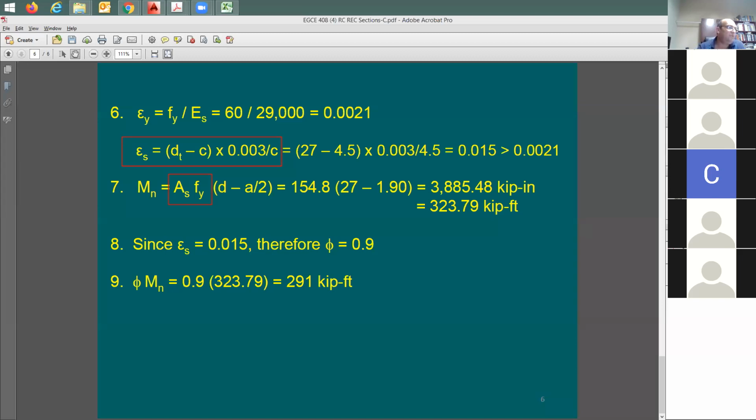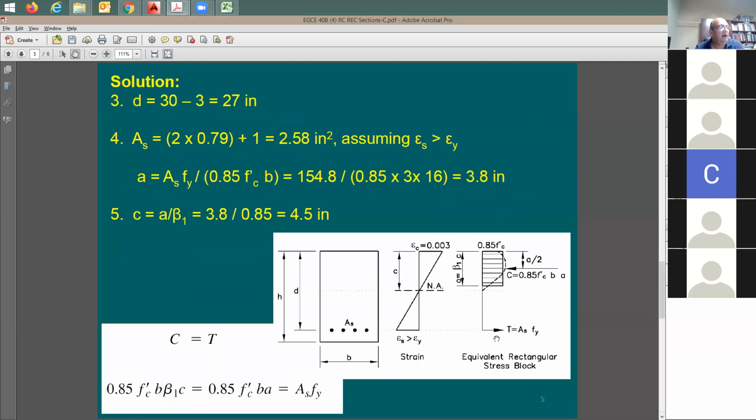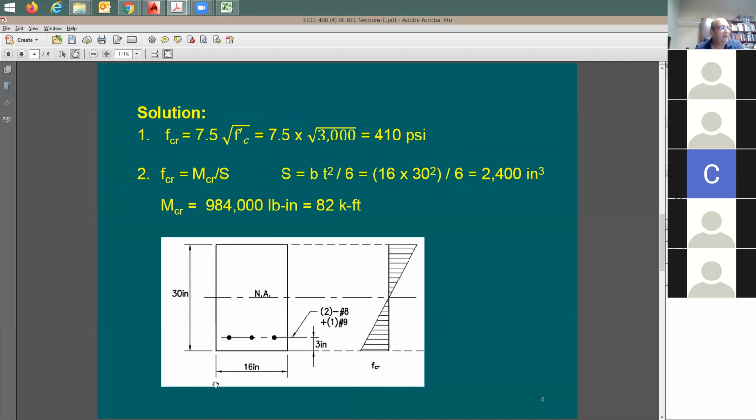Now let me continue. In your beam here, I give you the beam depth and width, and also I give you the reinforcing. In reality, you don't really have this. What you have is going to be the loads. You know the span of the beam, you know the dead load, you can figure it out, and then you know the live load. So you're going to be doing dead load and live load analysis. And with that, you're going to have the demand. Once you have the demand, what do you do next? You say, well, let me throw there some steel, since I don't know yet how to come up with the first estimate for the reinforcing bars, and then try and find out the capacity, and then you go through this exercise that we went through.